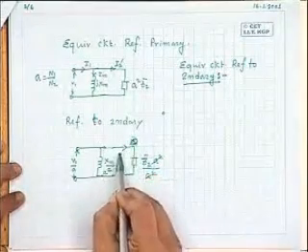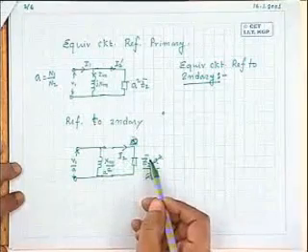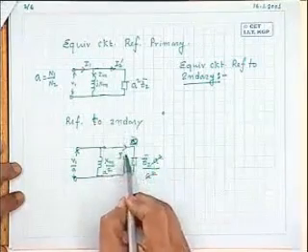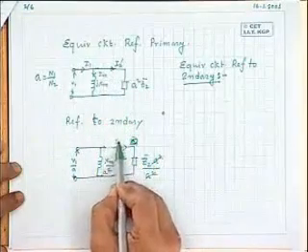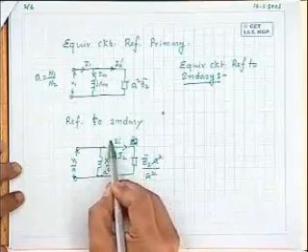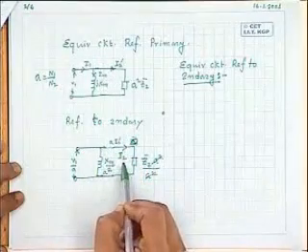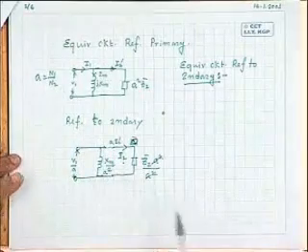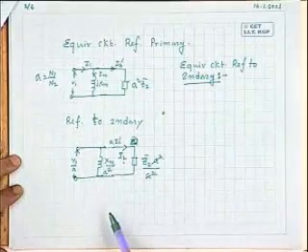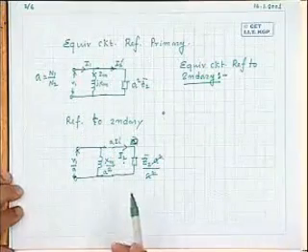This one, this is not Im. This is then I2, actual current, secondary side. Which will be how much? I2 dashed by A. This current gets transformed to, you have to multiply it by A. So you get I2. This voltage, you divide it by V1 by A. That's all. Clear?